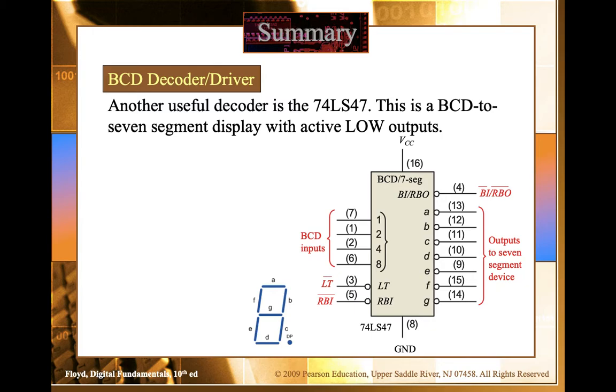So now the next topic, or shall we say the last topic in decoders, is the BCD to 7 segment display. This particular IC is very useful whenever we need to interface a 7 segment display in our system. So we use this particular IC in the middle. This is the BCD to 7 segment display IC, and then obviously the 7 segment will be connected on its outputs.